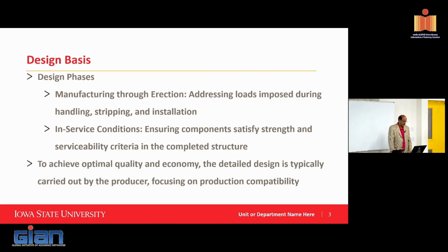The second bullet that I emphasize here is on precast. I see things differently here. In the US or in some other countries, the designer and the precast fabricator are not necessarily the same folks. As soon as the design is done, the precaster comes in, does a shop drawing, and does the component design evaluation. In that process, they also make sure that the detailing and the fabrication concepts come together to improve quality of construction. Obviously, if you're doing everything in-house, that's easier to tackle.